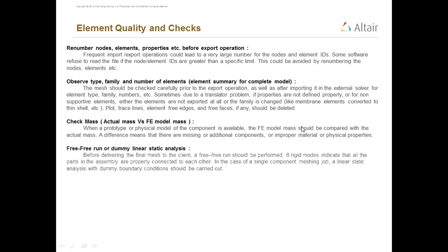Free run or dummy linear static analysis. Before delivering the final mesh to the client, a free run should be performed. 6 rigid modes indicate that all the parts in the assembly are properly connected to each other. In the case of a single component meshing job, a linear static analysis with a dummy boundary condition should be carried out to check the mesh quality and mesh connectivity.